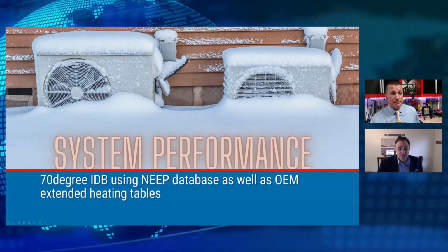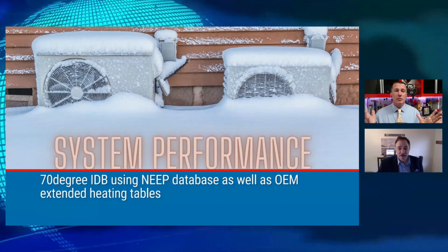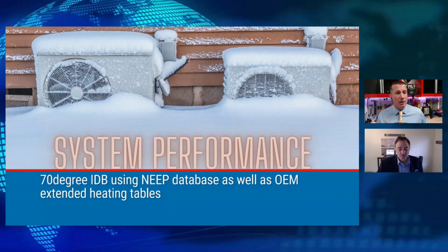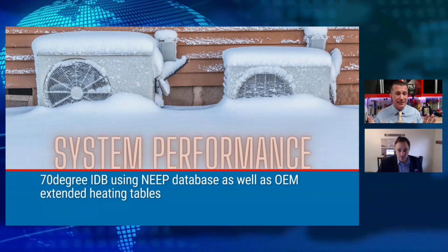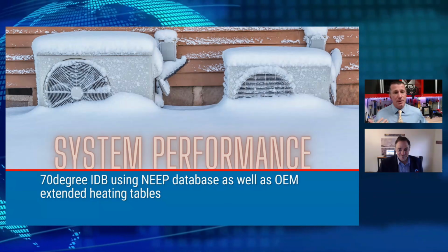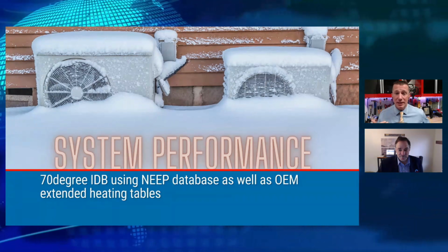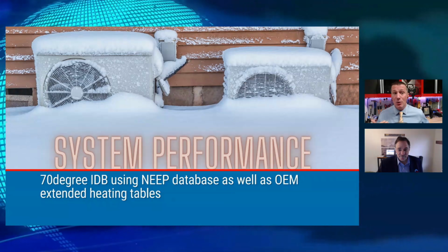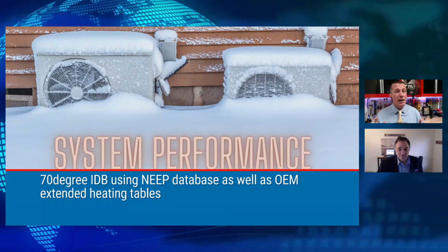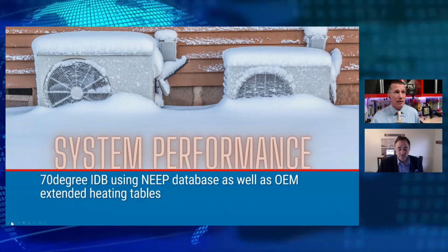So, Clifton, if my heat pump shuts off at 5 degrees, what are some of my options? Are you going to go into that too? So that's the biggest complaint that we see, particularly from homeowners that are buying heat pumps and doing their own installations, which I highly, highly do not encourage people to do. So when we look at heat pumps, and if we don't know what the rating is and what its capability is, we could be purchasing a heat pump that shuts off at 5 degrees, and if there's no backup for that, yeah, you're absolutely out of heat at that point. So it's crucial to understand the capability of the heat pumps when we're looking at our selections.